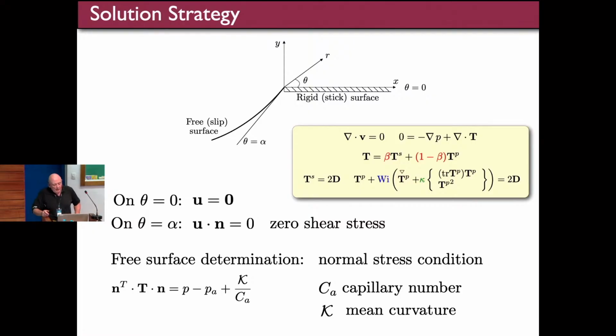Now, there's a third condition on the free surface, and that is the balance of the normal stress. And if you impose that on the separation line, then it's over-determined. And this was a result that was known back in 1952 by D.H. Michael for a viscous fluid. So separating from a straight line, a viscous fluid, if you impose the normal stress condition along with the other conditions, it can only emerge in the flat case. In other words, it can't be supported at an angle.